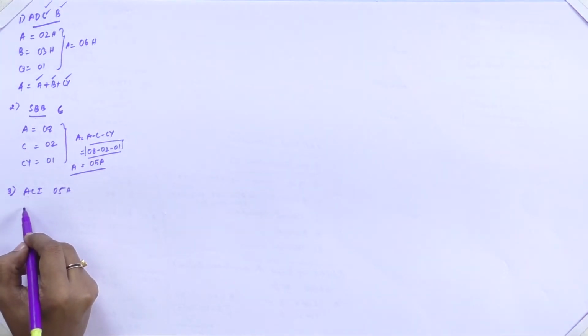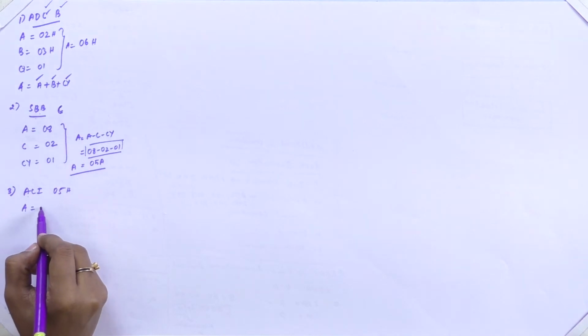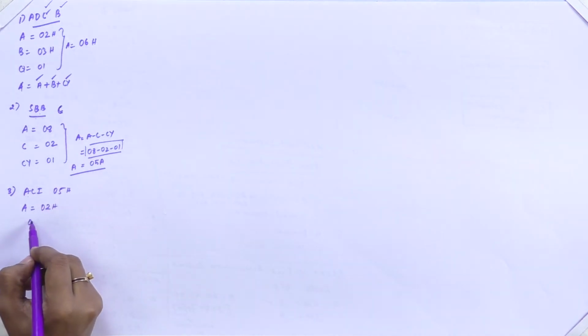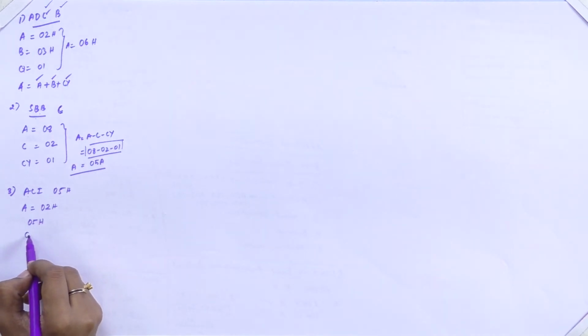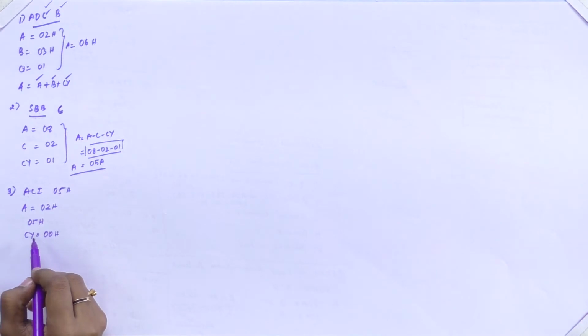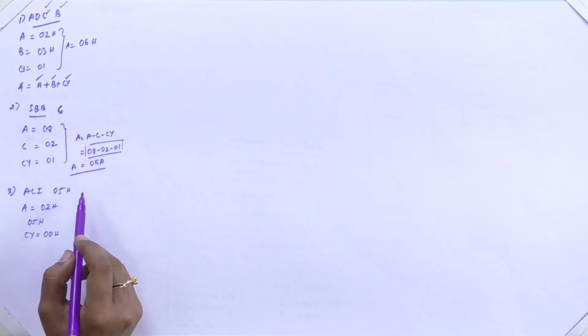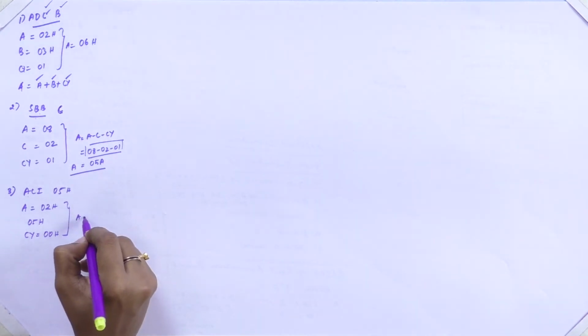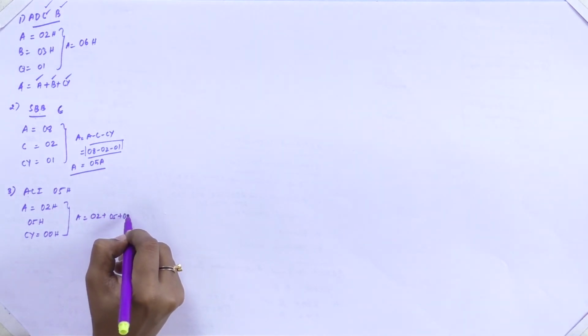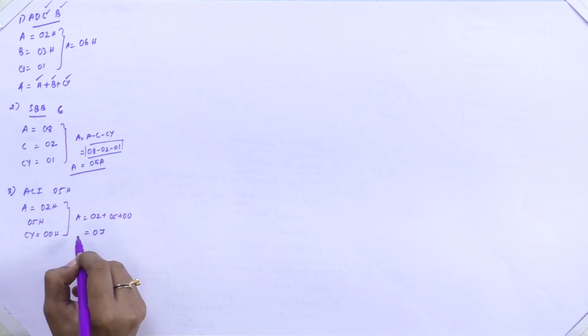It means that the content of accumulator, let us say 02H, the given immediate data and the content of carry bit, let us say 00H. Carry can be either 0 or 1. It will be added. So A is equal to 02 plus 05 plus 00. You get the value 07. It will be again stored in the accumulator. This is add with carry immediate.